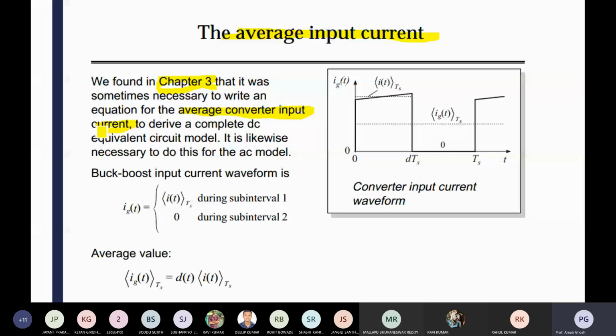Normally, the inductor is responsible in the boost converter for providing the additional energy. The DC voltage source is already there, and that voltage source is responsible for charging the inductor in the first instant. In the second instant, the DC voltage plus the voltage from the energy stored in the inductor are both added to provide energy to the output side. That's why you can observe more voltage in the boost converter. So what you can observe is that the inductor current is charging, then it is discharging.